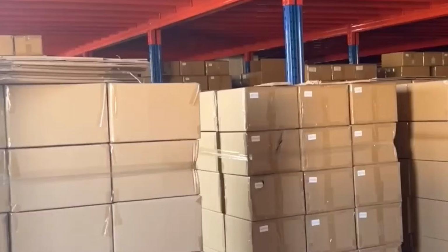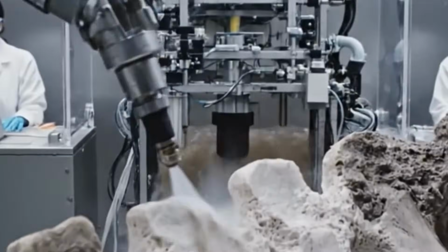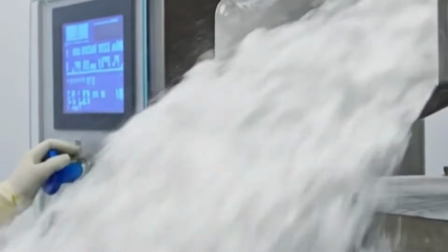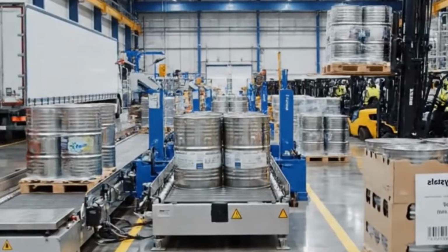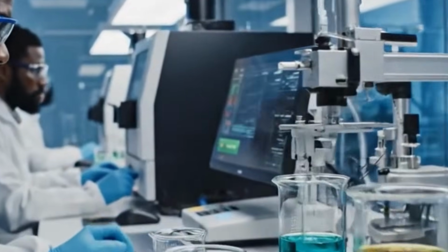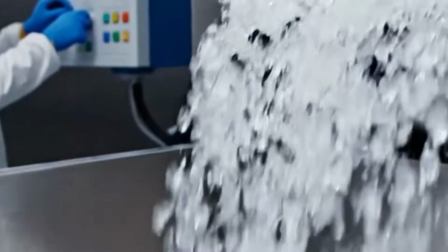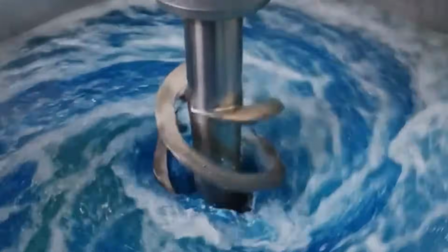Volumetric or flow meter-based filling systems dispense liquid into each bottle. Nozzles are equipped with anti-drip valves and may dive into the bottleneck to minimize turbulence. Fill volumes are controlled to within ±1 ml using servo-controlled pistons or mass flow controllers. Line speeds may exceed 200 bottles per minute depending on bottle size and product viscosity. Filled bottles proceed to the capping station.